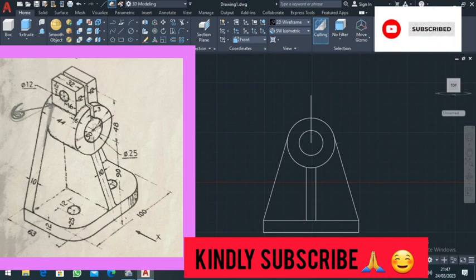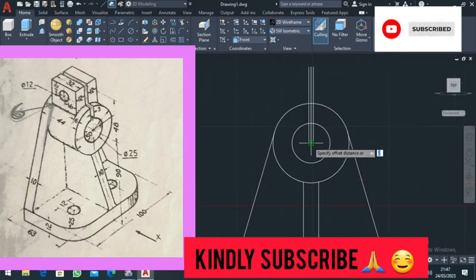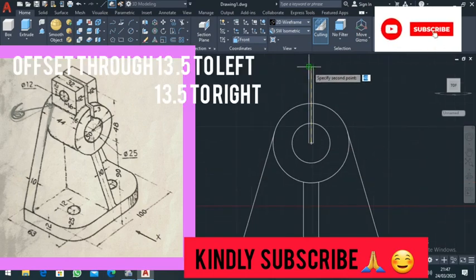The next thing you are going to do, you are going to come here and offset. This is your offset command. Specify the first point, specify the second point. After you offset that side for a distance of 1.5 millimeters, you also offset this side for a distance of 1.5 millimeters, as you see. From there, you are going to still come to the offset command. You come to this line at its start, specify, then you come to that point up. Then you are going to select the line and you offset it that side for a distance of 13.5.